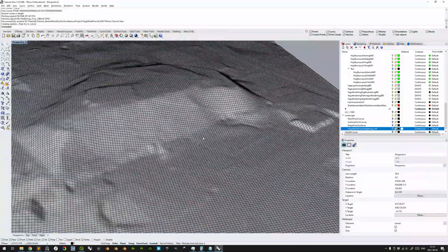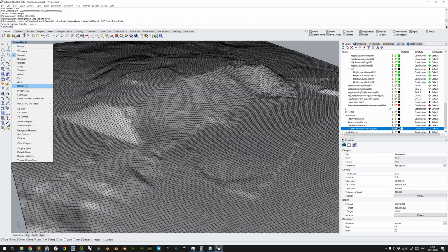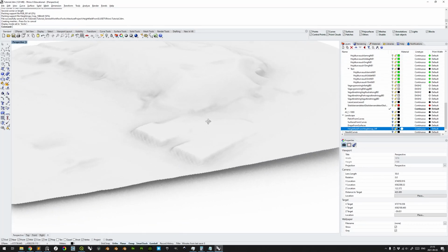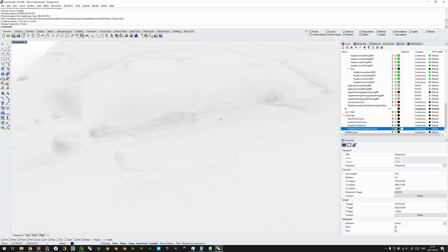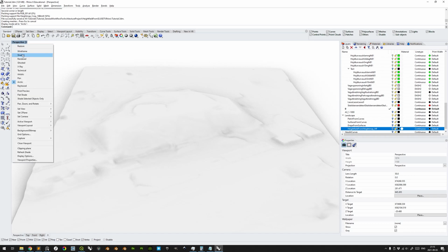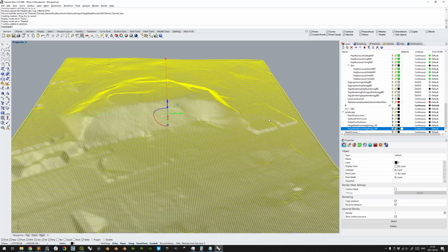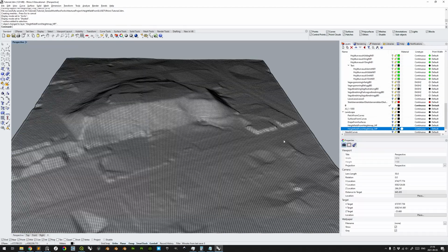Here the control curves are far less dense, while still retaining much detailing of the curvature of the landscape. We can determine that this is an adequate amount. We create another landscape sublayer called Heightfield from heightmap medium poly. Select the landscape, right mouse button click, and change object to layer.